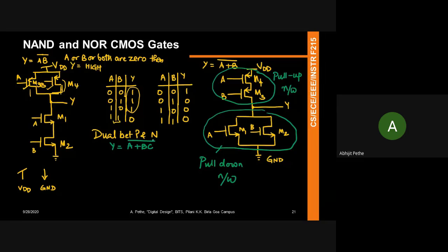So again, remember, you have done this before. When I asked you to do the NMOS circuit, you have done the pull down network. So the pull down network in the CMOS and the NMOS only technology remains the same, right? So all you have to do is find what is the equivalent pull up network for this. Following me?